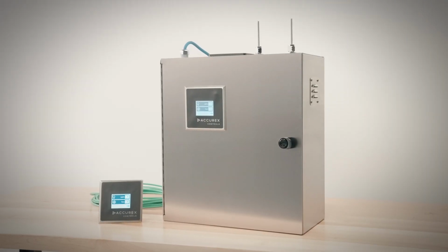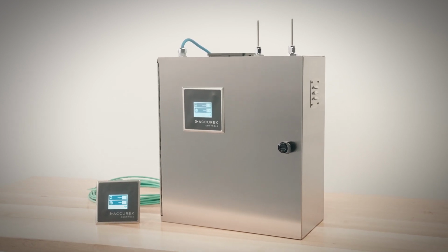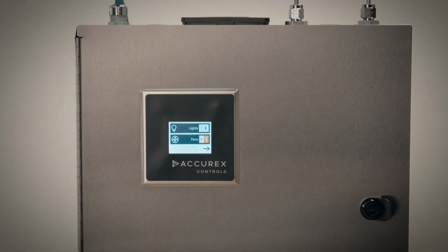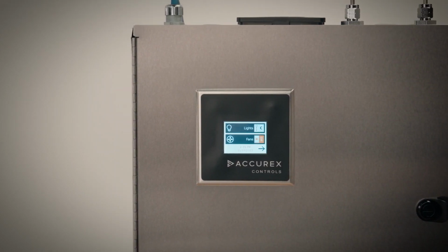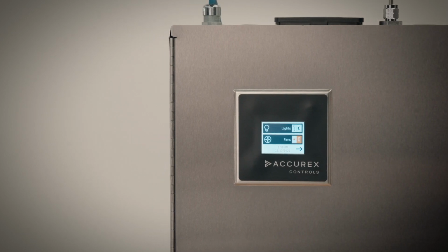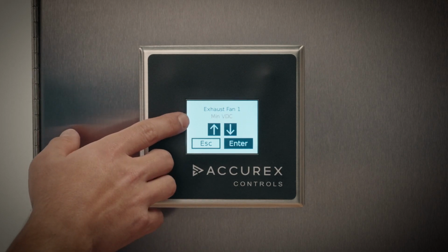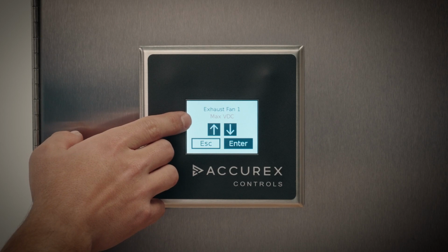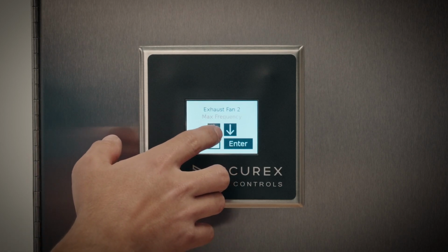The XKC series controller has the ability to control fan speed from the controls. In all control types, except constant volume panels, or CV panels with motor starters, the controls can adjust or are communicating the speed for the fans to run at. The exception is in constant volume panels set to run makeup air or exhaust fans with remote start. In these cases, any adjustment ability would be dependent on the makeup air unit or exhaust fan.